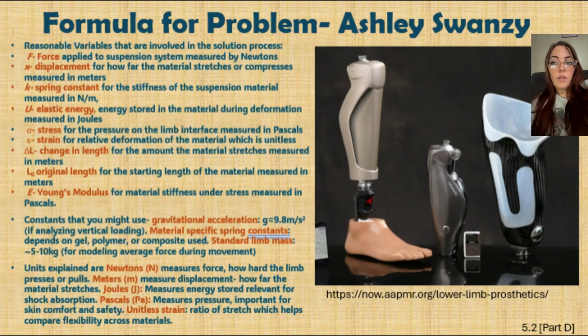You have strain for relative deformation of the material, which is unitless. Change in length for the amount the material stretches, measured in meters. Original length is for the starting length of the material, measured in meters. And then Young's modulus for material stiffness under stress, measured in pascals.